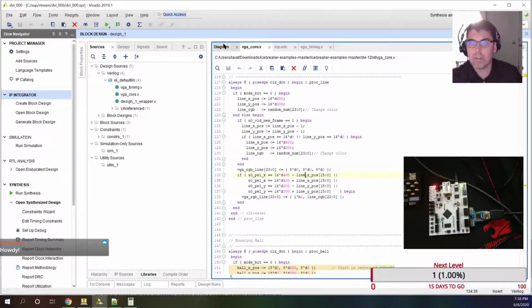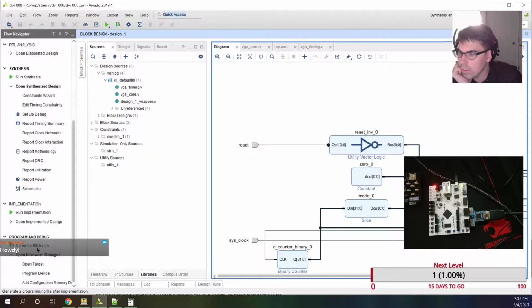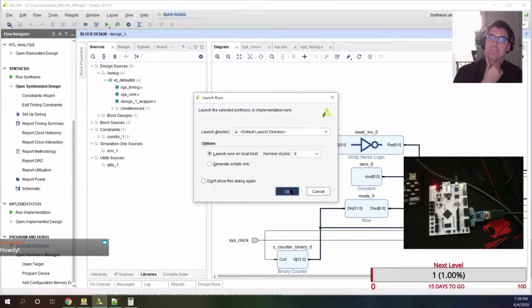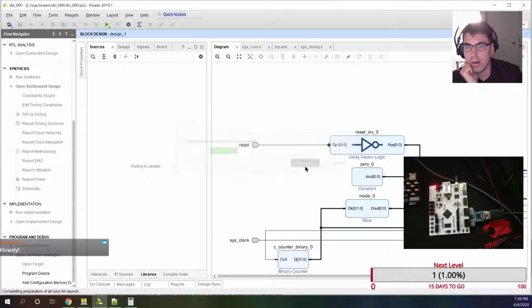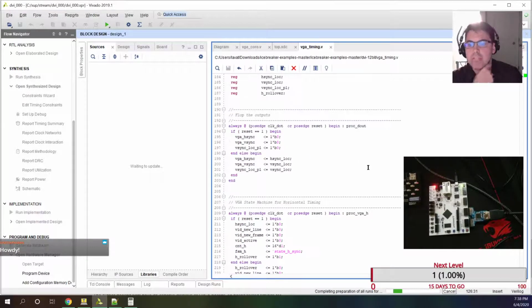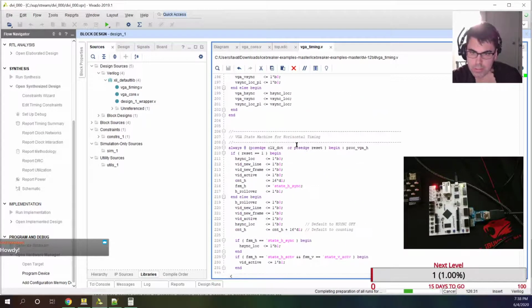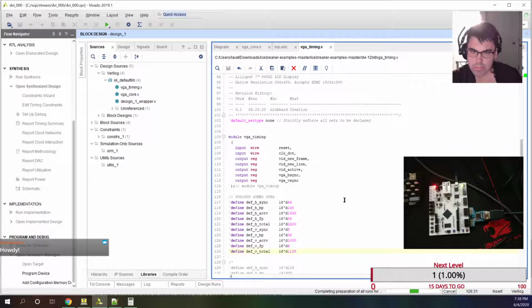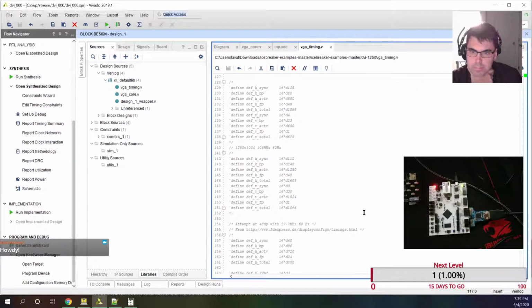So it's gonna be timed. Whatever, so we're gonna see if we can produce 1080p, then we just have to look at doing our own thing. Let's go ahead and generate this. So I'm probably going to make a VHDL module that takes an AXI stream input and outputs this video. Do we want to configure resolution? We probably should just have like being able to reconfigure resolution, right? Some parameter that goes through all these things.